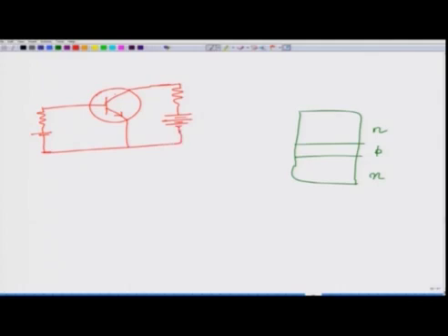Okay. We are talking of this circuit here, and the working is that when you forward bias this, then you have a lot of current, a lot of charge carrier injection of majority carriers. So, this injects a lot of electrons across this depletion layer, across this junction here, and then most of them are collected, let us say, by this collector. Of these electrons, a lot are collected here, and therefore you have a corresponding current.